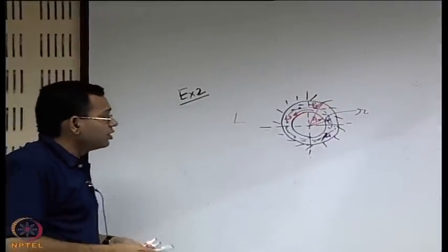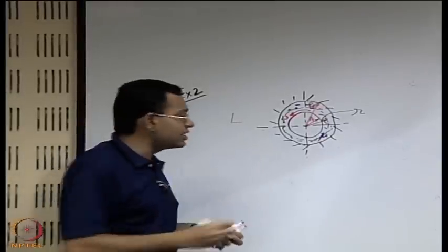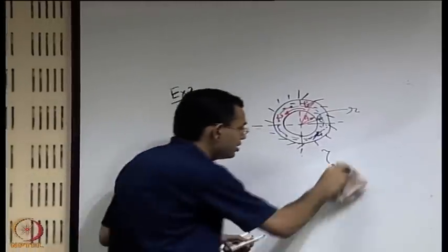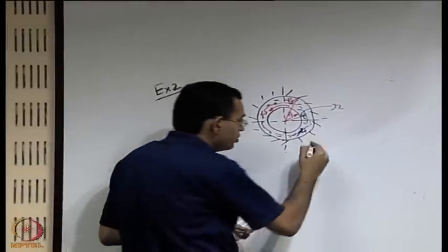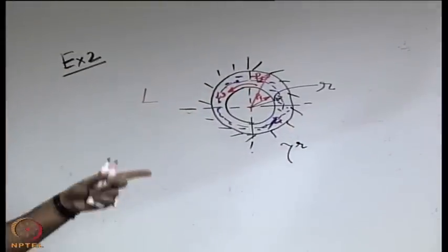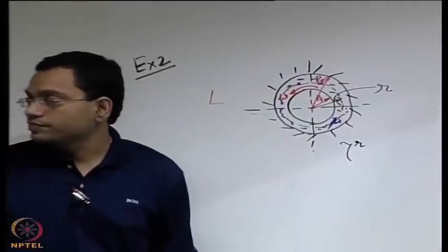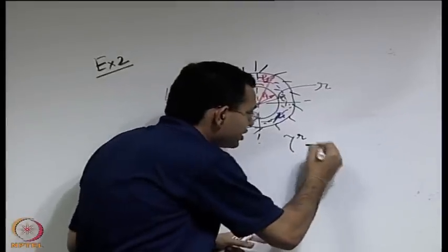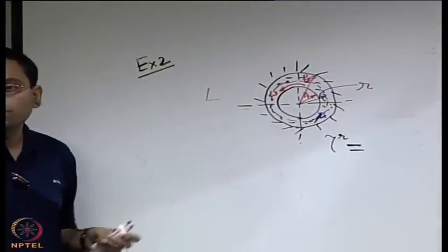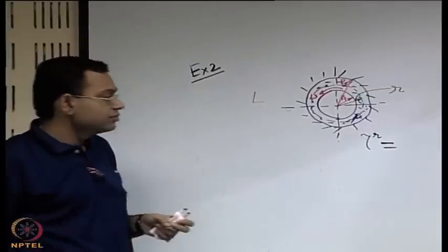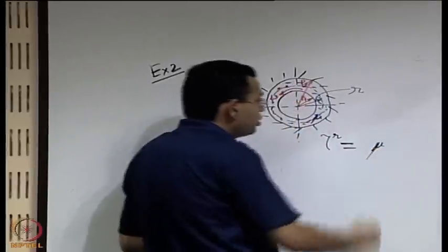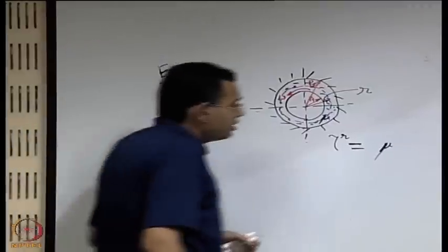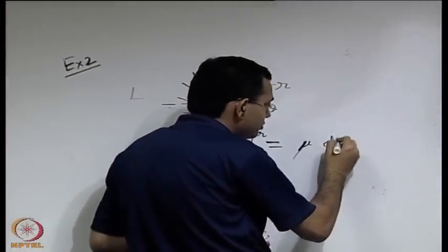of deformation. So if we want to write the shear stress at the radial location r, we should maybe use a superscript because it is not really tau with r as a subscript, meaning we have preserved that for something else. So if we write this, then what would be its corresponding expression in terms of Newton's law of viscosity? There is a mu, there is some sort of du dy type of term. So what is, let us call it some du